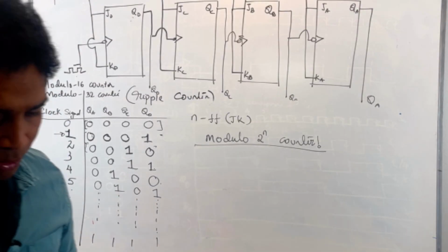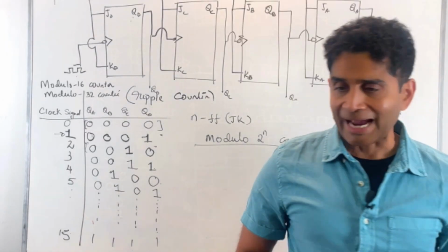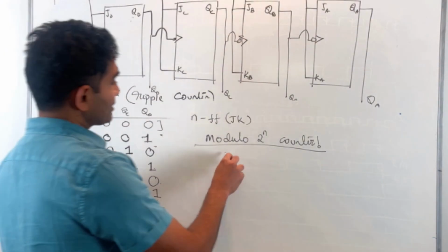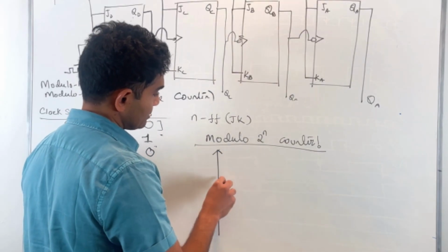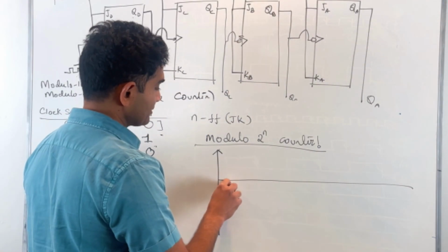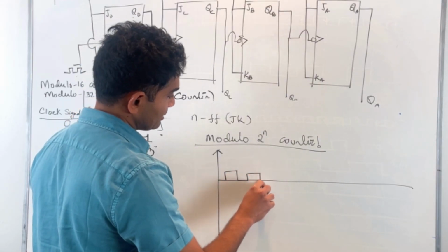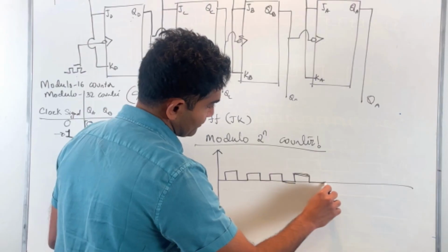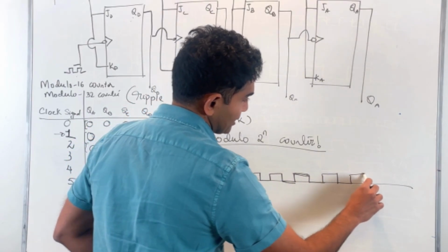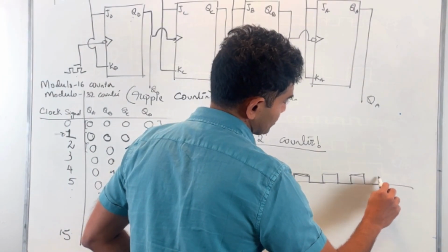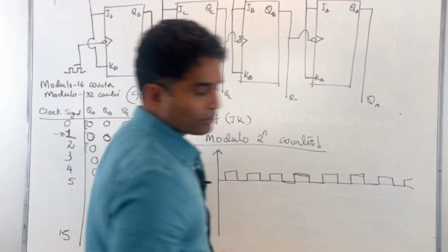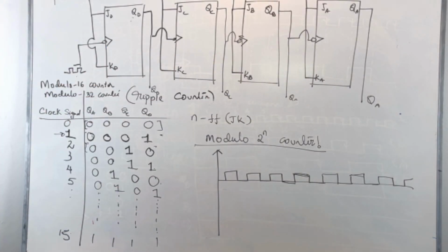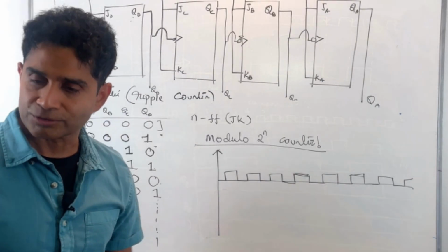Again, similar to what we saw for an n-bit adder, we would have a similar problem here. If I look at the timing diagram again, this is the master clock being applied to the first flip-flop only. So in general, it's not good practice to introduce logical elements in the path of the clock, just like what we have done here, because that can throw the circuit out of synchronization.